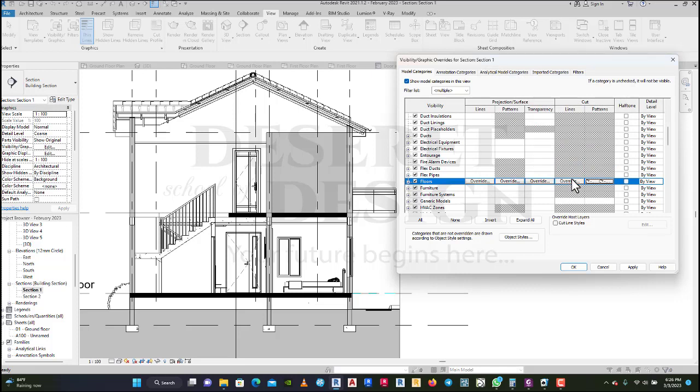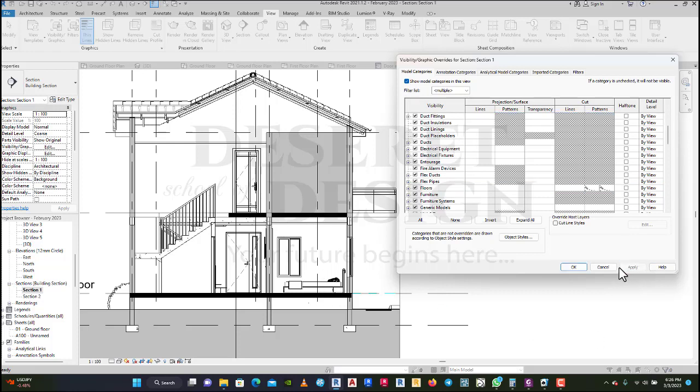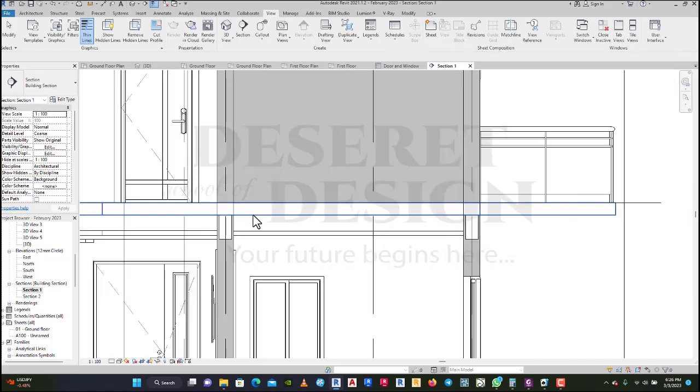Now you may also want to change the line pattern. I will not talk about this now. I'll talk about it when we get to object style, where I will explain how every item has its default line width. You can even tweak it there. So I'll leave it. Now I'm going to apply the changes I have made. So we'll be looking at all my floors, every floor I've cut. If I apply, now you see my concrete floor. Let me click on OK. Now you can see the concrete floor.